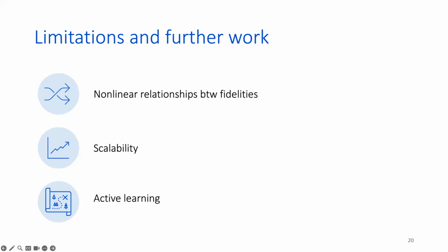We're using the fact that Gaussian processes can be easily updated with new station information without having to retrain the whole model, unlike a neural network. So you could set a hypothetical new station location with data and see how it minimizes the uncertainty for the whole basin, and then optimize for the ones that reduce the uncertainty globally.